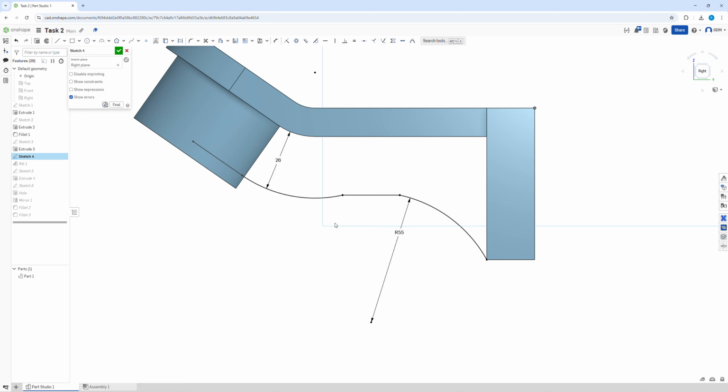Now it's fully constrained, which means some of our constraints here are not helping us. So that's probably going to be an issue. It is. We can move that one, and we can now move this part and this part. Press T on the keyboard and make those tangent. That does not look that smooth. So if I take away, let's see if it's that constraint. What else have we got? And take away that constraint. Now we want those to be snapped, but we want them to be tangent as well. So click, click, press T. There we go. That makes that tangent.